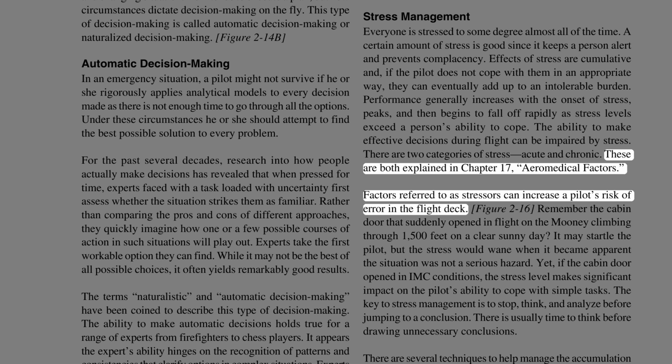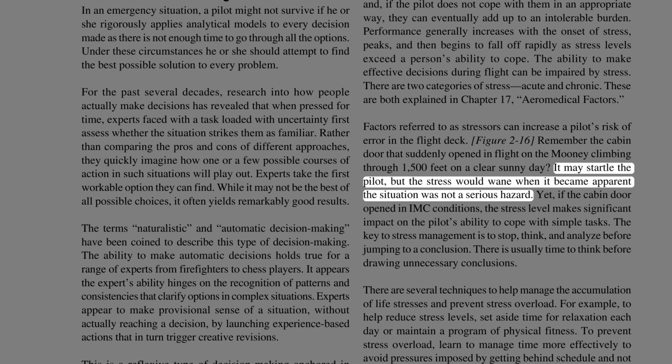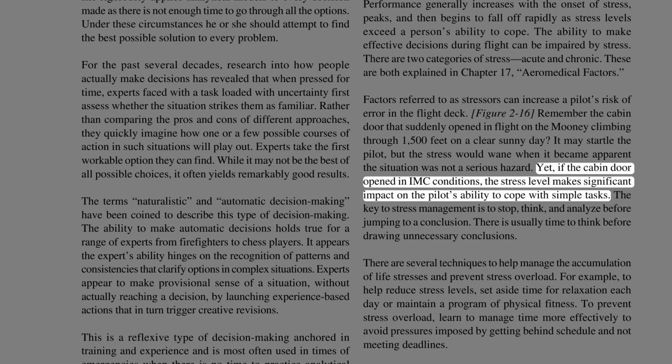Factors referred to as stressors can increase a pilot's risk of error in the flight deck. Figure 2-16. Remember the cabin door that suddenly opened in flight on the Mooney, climbing through 1,500 feet on a clear sunny day. It may startle the pilot, but the stress would wane when it became apparent the situation was not a serious hazard. Yet, if the cabin door opened in IMC conditions, the stress level makes significant impact on the pilot's ability to cope with simple tasks.